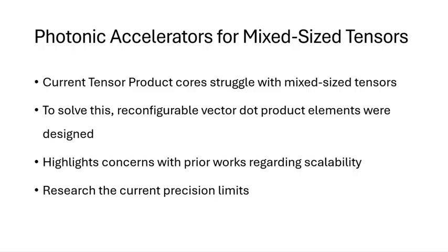For processing flexibility, if the employed accelerator hardware supports more parallelism than necessary, it can lead to lower hardware utilization efficiency. And for parallelization for tensor processing, determining reaggregation size based on the smallest and most common decomposed kernel vector, again, maximizes the opportunities for processing parallelism. And for energy efficiency, efficient parallelism and hardware utilization increases energy efficiency as the energy drawn in is used more towards the computation instead of through static power consumption.